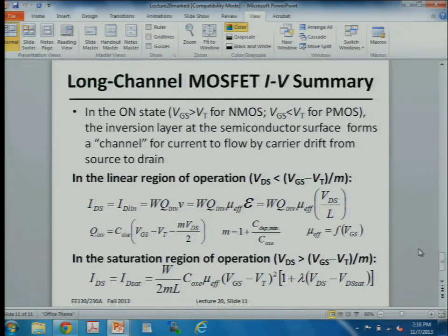Starts at the source potential on the left, goes to the drain potential at the right. So on average, this is an easy way to remember. On average, the channel inversion layer is like halfway between the drain and source voltage. So we have this minus VDS over 2 factor. Okay, but because of the bulk charge effect, you have even less inversion charge than the ideal case.